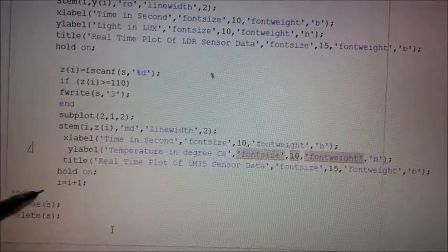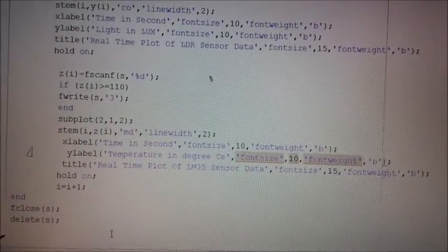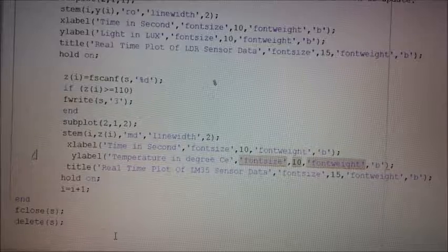And here we close the port and delete the port to take the next action. Here we run the program in Energia. After running, it compiles and uploads to the microcontroller, and when we see erasing program and done, that means your program is successfully loaded.